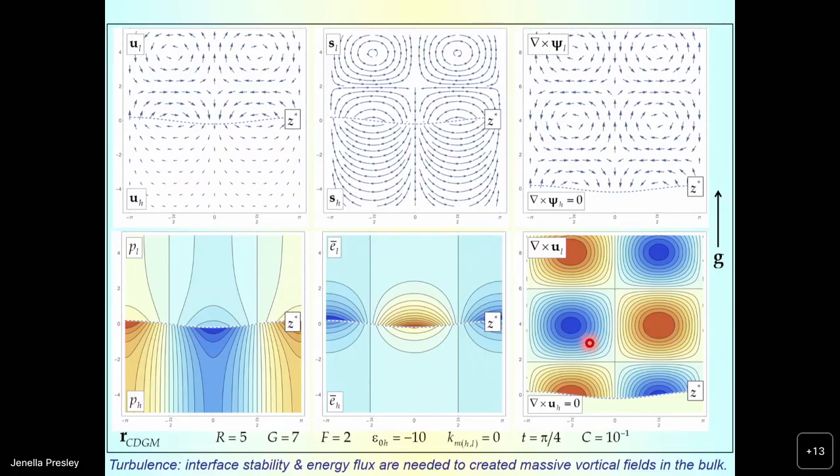And when we compare these results to our previous results, I would like to put forward a somewhat provocative hypothesis. Traditionally, people think turbulence is created when we have a laminar flow that moves very quickly. In this laminar flow, we should start to develop instabilities, and as soon as the instabilities occur, they immediately lead to turbulence. In fact, what we see here is that as soon as the dynamics is interfacial, it remains interfacial. As the interface grows, whether it is an interface with mass flux or with zero mass flux, like in Rayleigh-Taylor, it's essentially interfacial. So the maxima of all the quantities occur in the vicinity of the interface and decay far away from the interface.